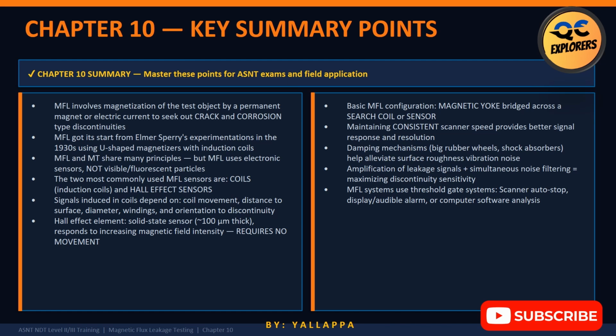Fourth, MFL and MT share magnetic principles. But MT uses particles. MFL uses sensors. This distinction appears repeatedly in ASNT and PCN exams. Fifth, the two major sensors are search coils and Hall effect sensors. Memory shortcut: coil moves, Hall stays. Sixth, signal quality depends heavily on speed control, vibration damping, and signal filtering.